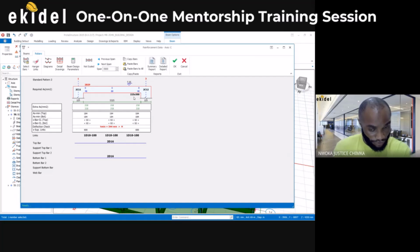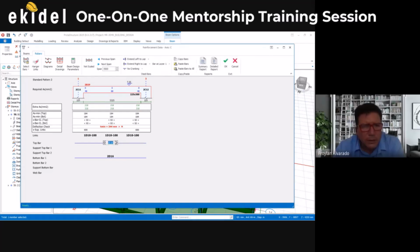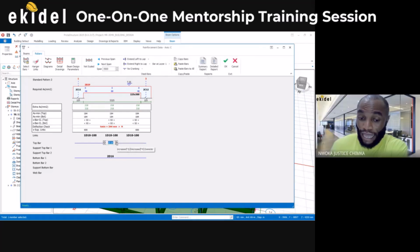Can you see that? Yes. So that's what is failing it. It's failing based on what? Deflection and all that. So either we increase the depth, although most times you can choose to use a bigger size reinforcement bar to control the deflection, but most times that is not also advisable. You just use the depth to control that.